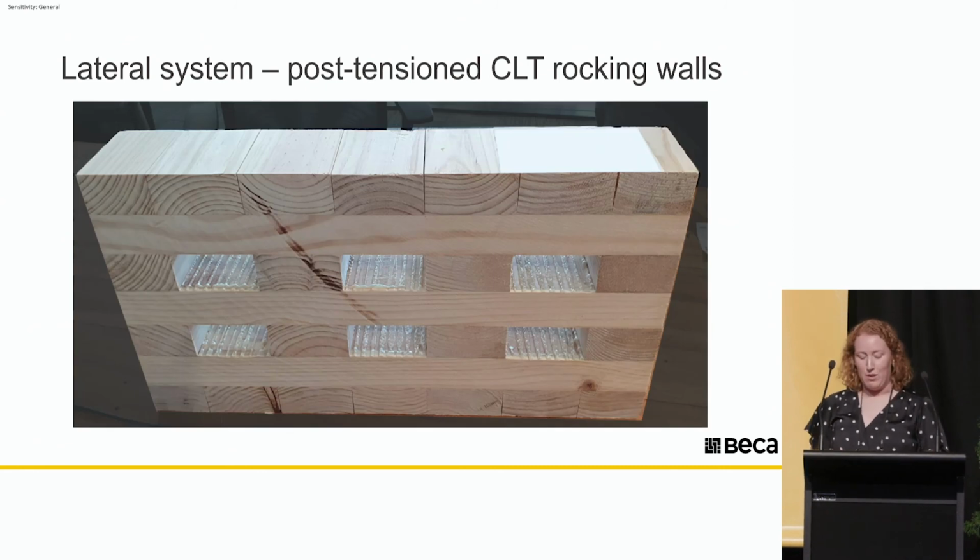As the post-tensioning layout was critical to the analysis, we needed to figure out the construction methodology for this early. We worked with CLT suppliers to develop this, and here is a sample that the supplier put together. To create the ducts, they remove laminas in the CLT wall during manufacture, and so we'll have these nice big ducts down the middle of the walls. Including the timber suppliers in this conversation was very important, as their lamina widths and lengths were all changing, and it was important to make sure we could actually build this.